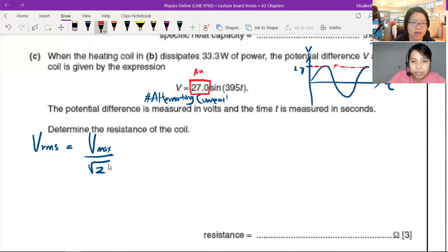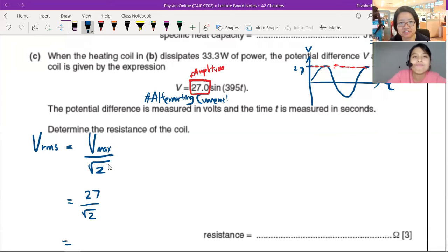The idea of root mean square is we are trying to find a way to find the average for this graph. But the problem with this graph is if we take the absolute average, you're going to get 0, because your positive got negative, your average becomes 0. And no current, GG. So actually got current. And the resistor doesn't care about the direction of the current. The resistor just says, you give me current, I will heat up.